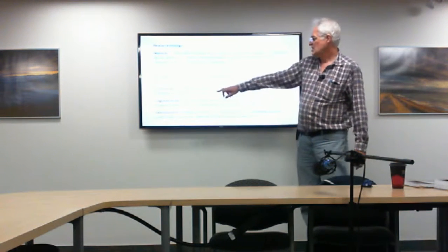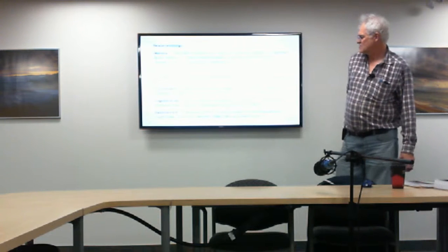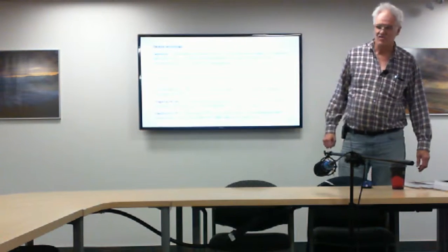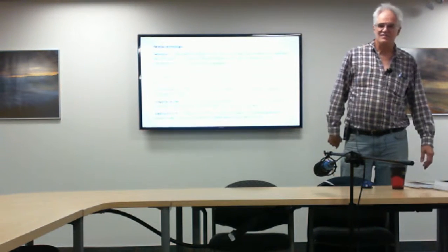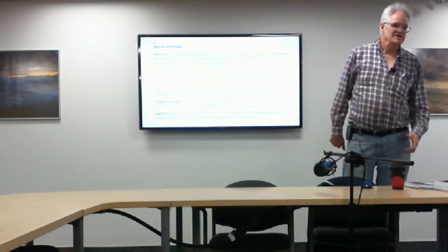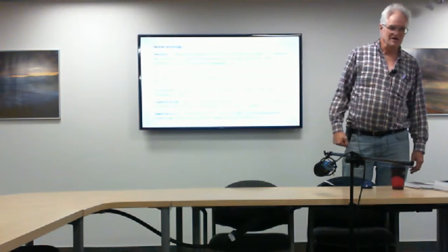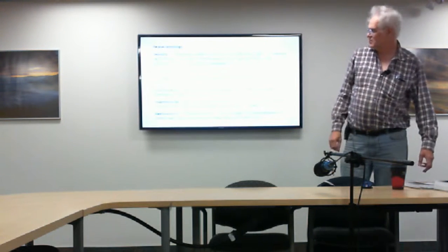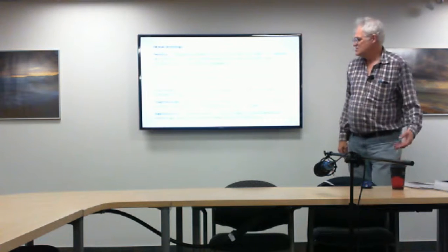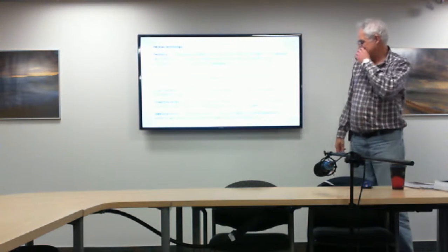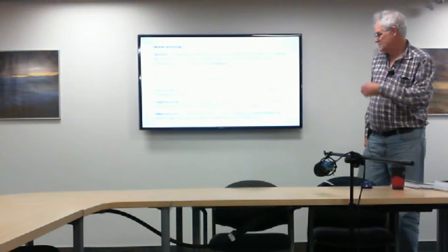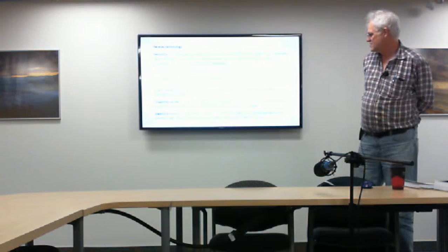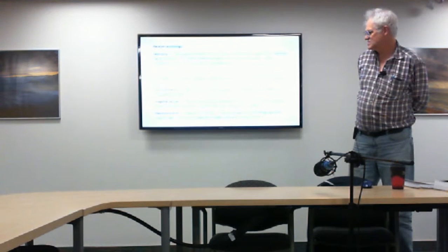A term called cross-modulation occurs when the incoming signals overload the receiver's front end, or it's sometimes also called receiver overload. You'll actually find that if a couple of us were leaving here tonight and one of us was to transmit on our radio in their car, anybody fairly close would find their receiver almost swamped or muted because the signal's so strong. Image frequencies, we'll talk about in a little bit more detail. They're strong signals at a particular but different frequency than the frequency we're tuned to.